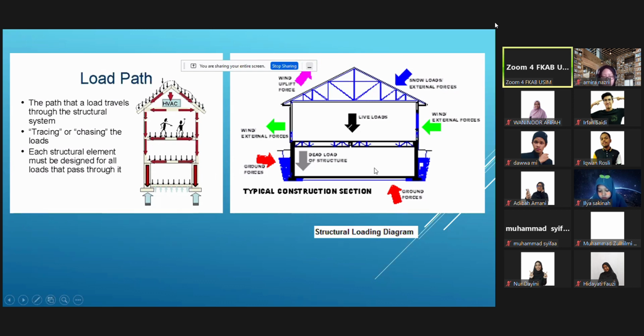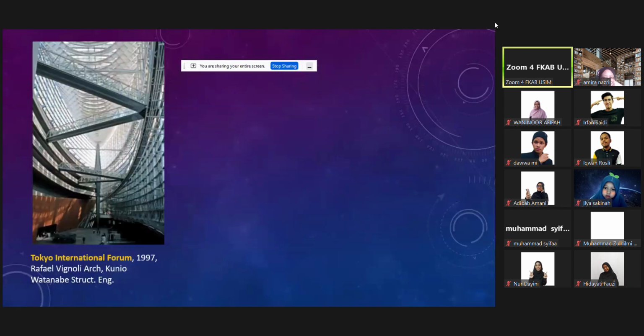So the tank was pushed up and floated on the ground. Even though the tank's foundation already had piles and was tied with a very nice piling frame. But why? Because the tank was empty, so there was buoyancy. If the tank is full of fuel, okay, no problem. That was one of my experiences there. But actually the contractor had to redo the whole thing. Okay, this is another example of the forces.